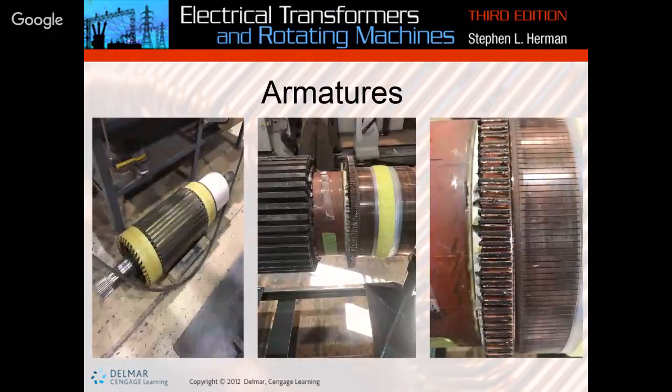Okay, here's what I was looking for. Here is a picture of the question that you asked. The slots here are essentially another loop that's going to go over to the back side of the cylinder. This is an actual armature pulled out of the frame, and it's getting rebuilt. This is the commutator itself. Each one of these little paths right here is a coil. Here's the end of the wire, a big, huge chunk of wire in that inductor.